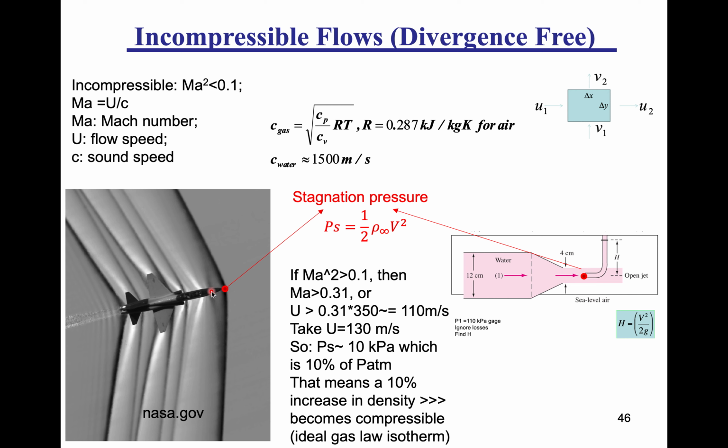What we see is that the air that is close to the tip gets compressed, and we get those shock waves. And a shock wave is just a fluid of increasing density. It's a rise in pressure. That's what a shock is. A rise in pressure means also a rise in density, as you can remember from your ideal gas law. And we see multiple shocks that come out that surround this aircraft.